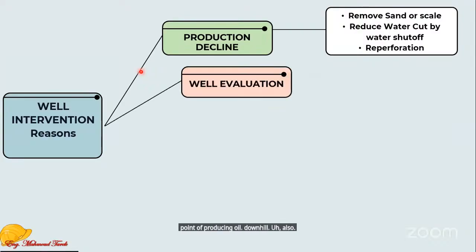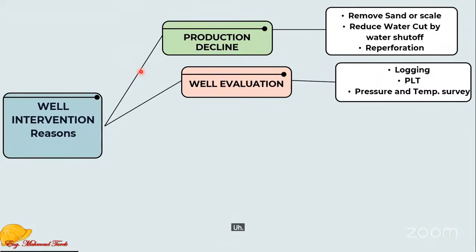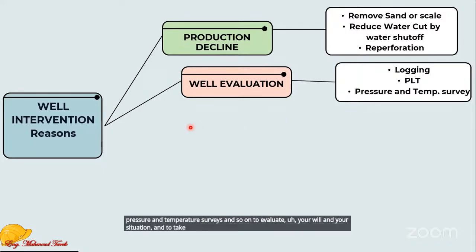Also, well evaluation. During the well life phases, you must know the production rate, the pressure and temperature of the reservoir to design your upcoming operations. So you need those data by logging techniques and PLT, production logging tools, pressure and temperature surveys, and so on, to evaluate your well and your situation and to take the right decision for the upcoming operation.